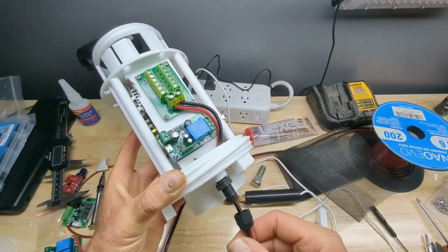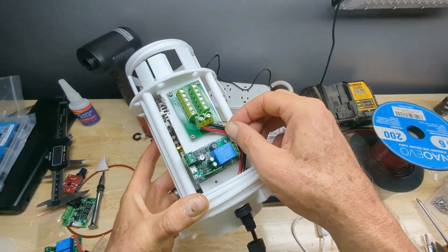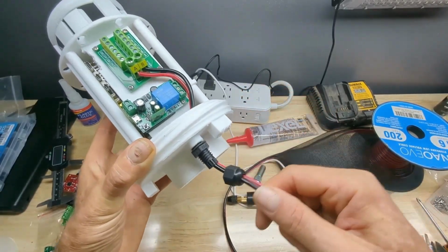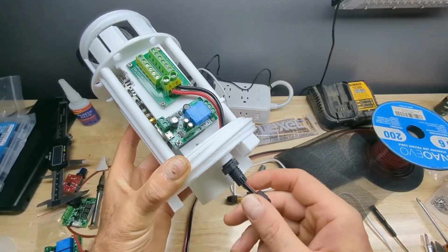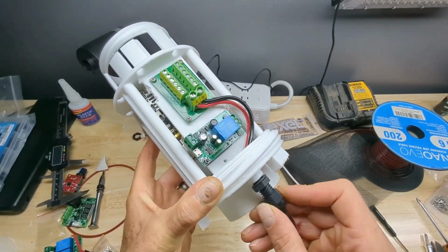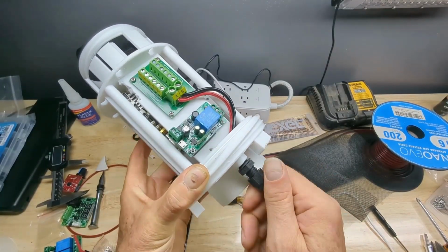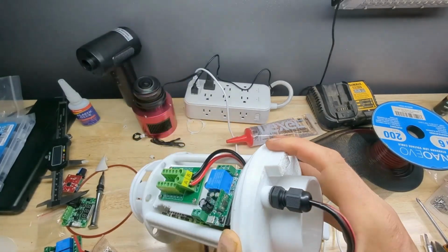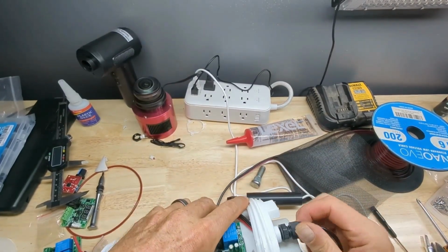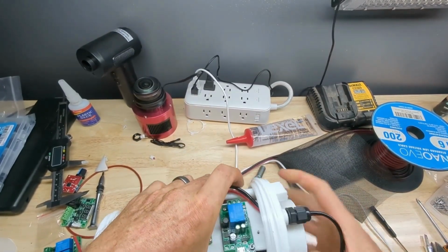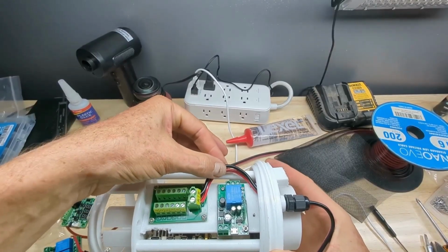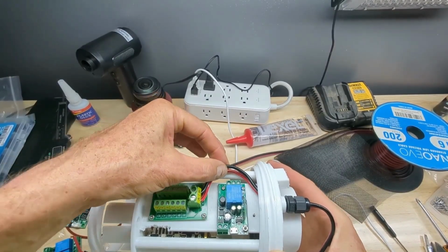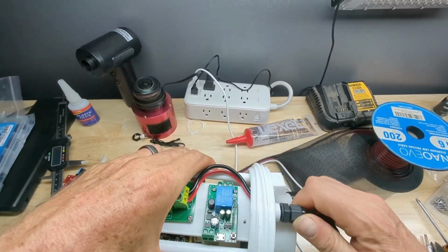And you don't want to have any kind of a situation where these things could get loose, because this cable is continuously being yanked when it's not secured. So just push that up on there and tighten it up. As you tighten, it will tighten those fingers down, and you'll see you have already a little slack left in here just in case, a little stress relief on the cables. But once you tighten this up,